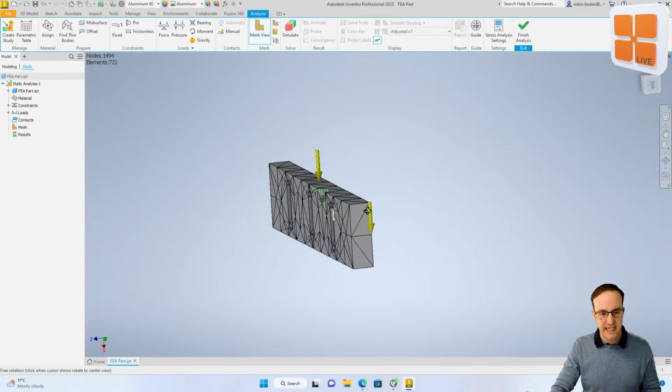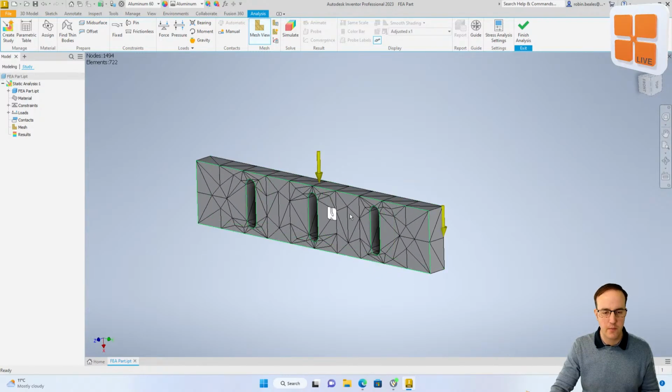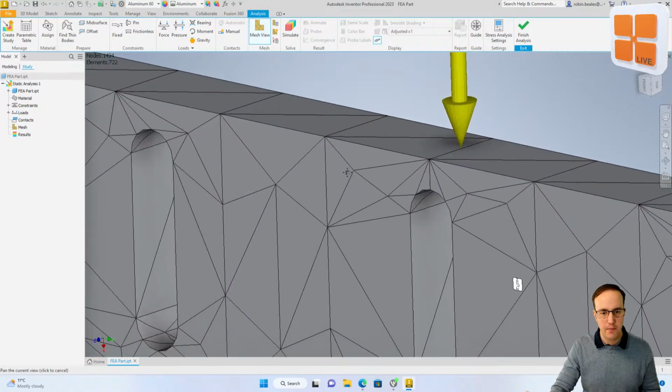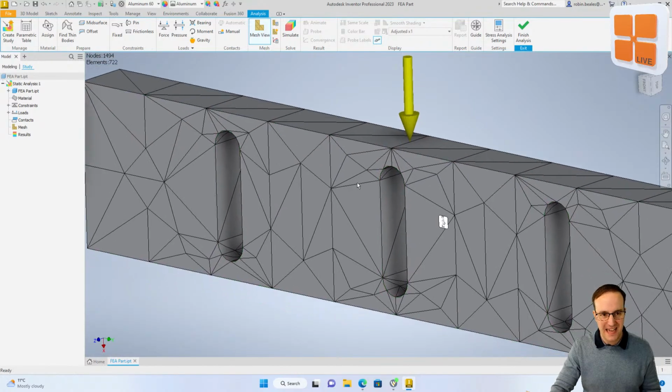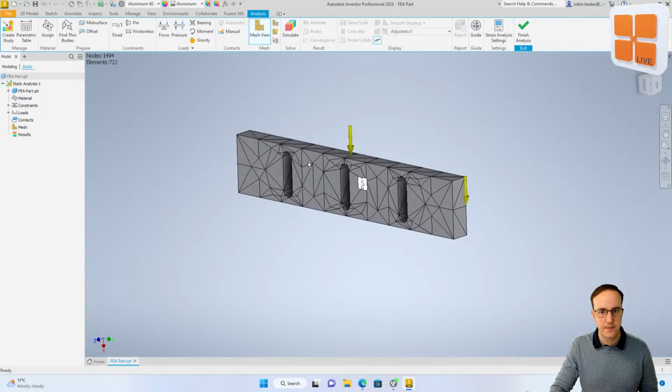The thing to bear in mind is the size of that mesh. Now this is a pretty generic, rubbishy example if I'm completely honest. So the actual triangle size isn't going to matter that much, but the triangles you see here are representative. They're not actually true to the shape of the actual mesh. That said, the more refined your mesh, the better results you're going to get. So if you were particularly keen on looking at the displacement of these curvature faces, you would want to do some refinements, which we will do in just a second.